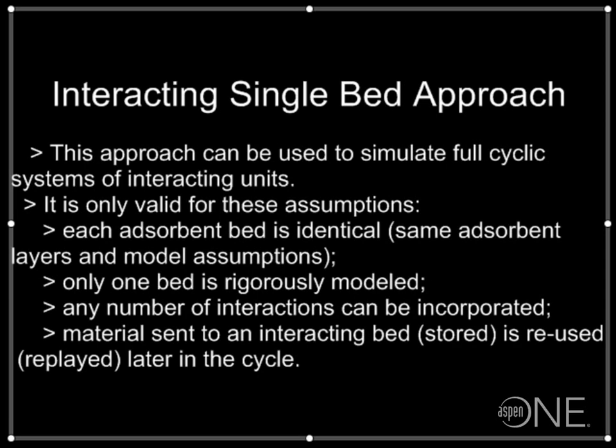The interacting single bed full flowsheet can be used to simulate full cyclic systems of interacting units. The flowsheet makes use of the interacting single bed approach, and this approach is only valid for adsorbent beds that are identical. They have the same adsorbent layers and use the same model assumptions. Only one bed is going to be rigorously modeled.